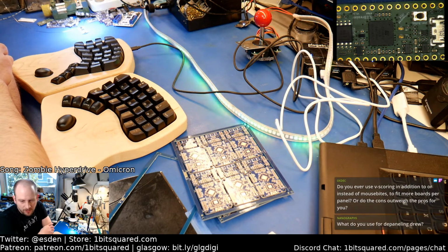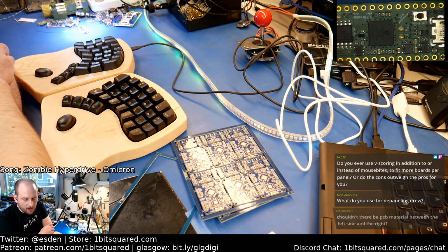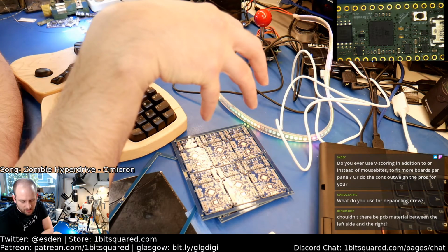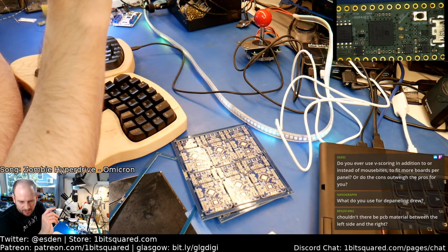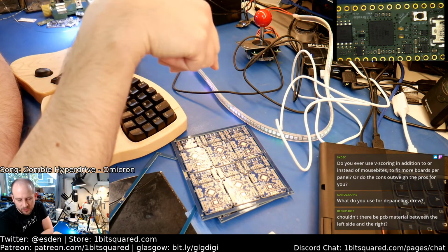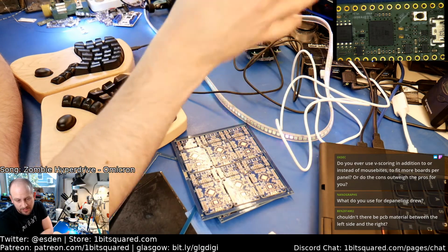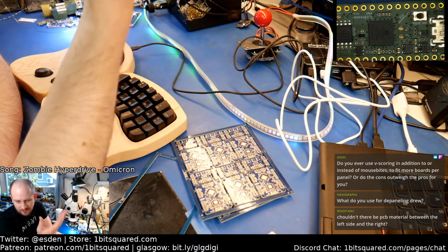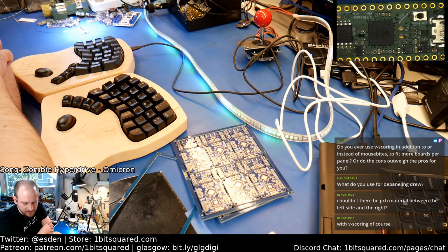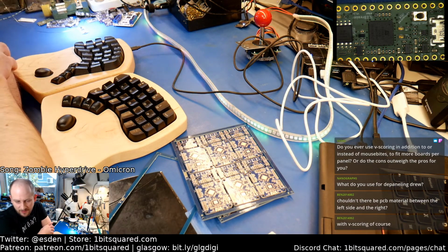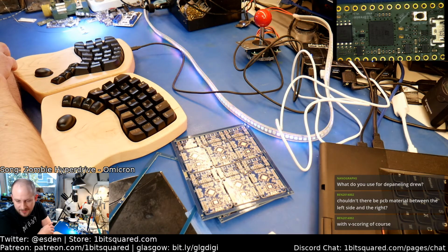But most of the PCB manufacturers these days actually have smaller router bits by default. I have not had any complaints since I switched to a 2mm gap. And a 2mm gap on panels and in quantity eventually adds up to quite a lot of saved PCB space. So it is nice to save some space, some material, and some money.